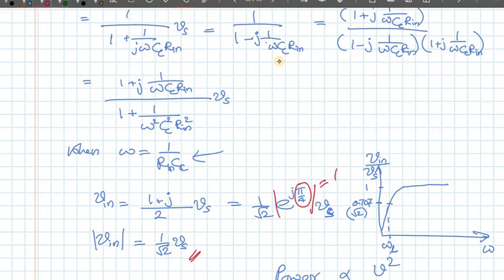So at very high frequency, this will roll off from the other side also. The frequency at which that happens we call the upper cutoff frequency, omega U. This is due to parasitic capacitance at the base-emitter, base-collector, and collector-emitter terminals.